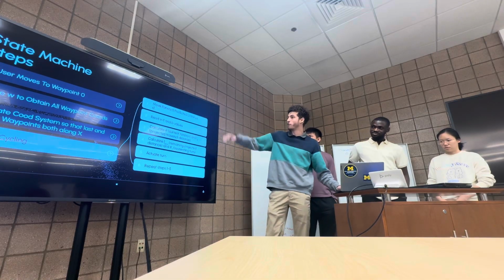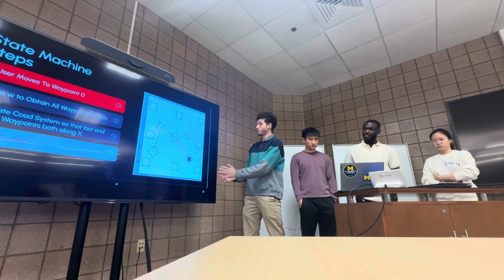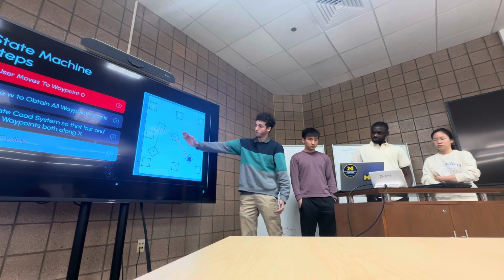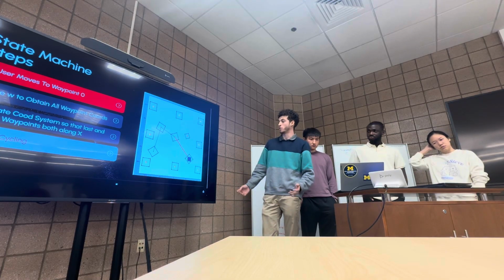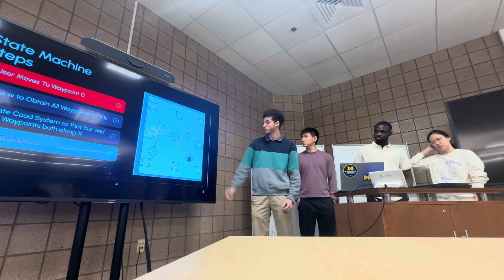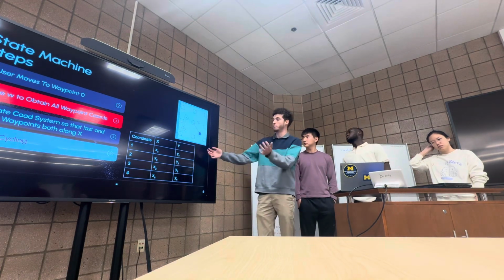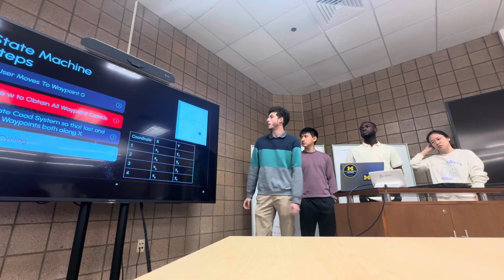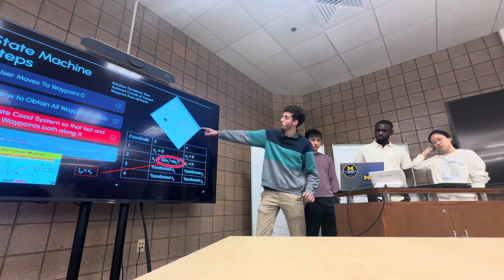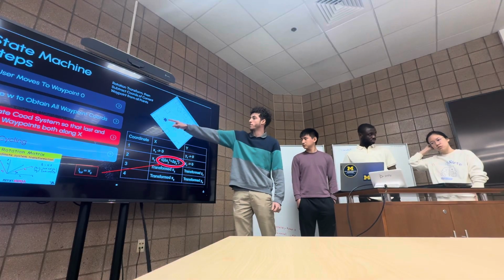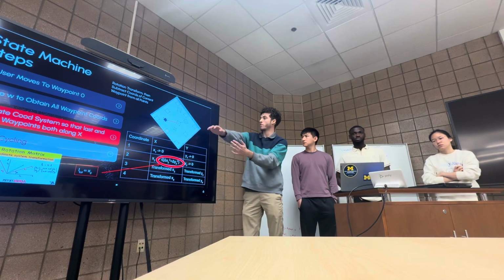So here's the general flow of what we're going to do. We start by manually moving to waypoint 0. In reality, we probably want to angle our robot as far along the spine as possible, but for the sake of making a good visual demonstration, let's just say we move straight south to north. Our robot comes here. We then obtain all the waypoints. It's just going to be a list of coordinates in centimeters. And then what we want to do is rotate this whole system so that when we're moving from waypoint 0 to waypoint 1, it's just along the x-axis.